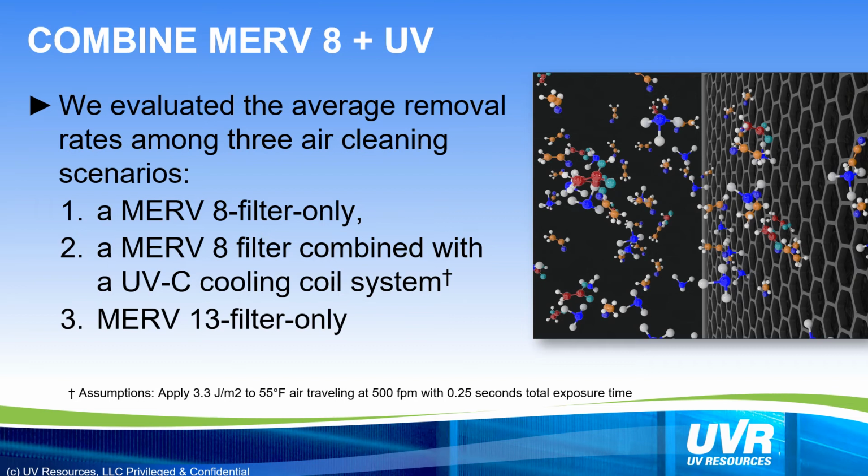However, not all AHU systems, particularly the large number of aging systems, can handle the high airflow restrictions and static pressure of MERV 13 or HEPA filters. So, working with microbiologist Wally Kowalski, who literally wrote the handbook on UVGI, we modeled 3 separate filtration options.